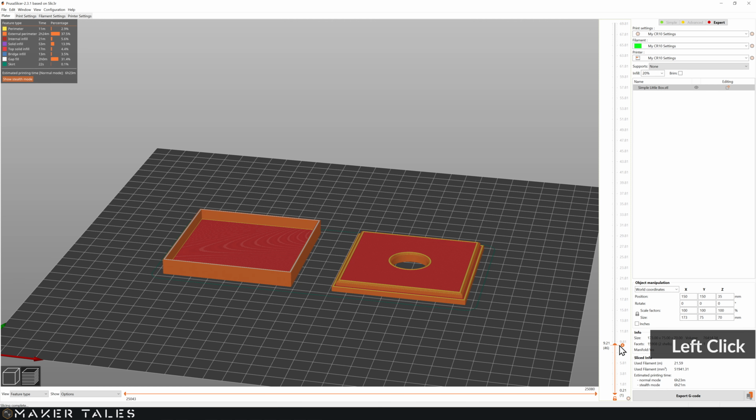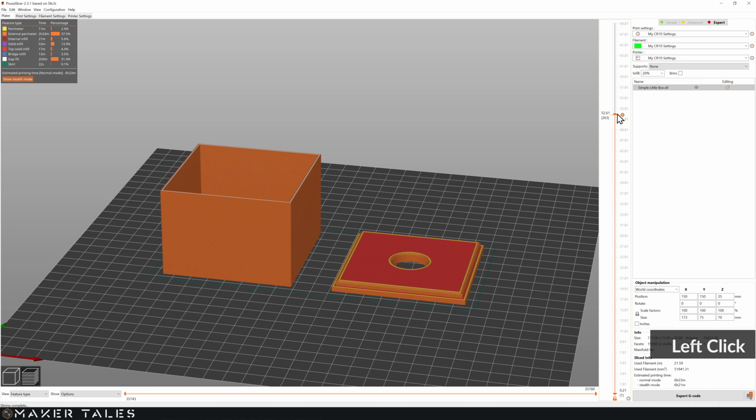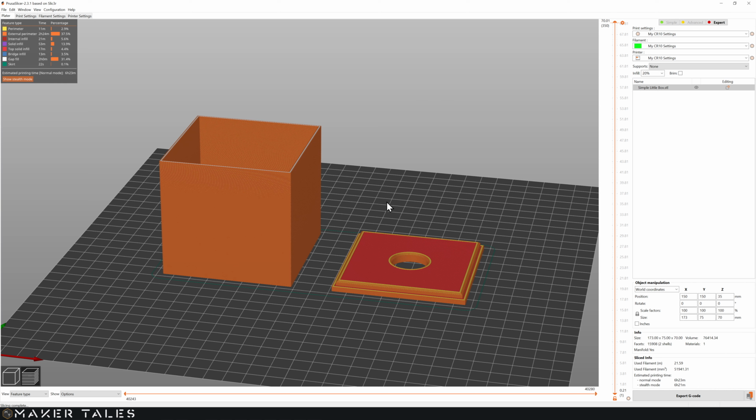That's perfect. There you have your first 3D printable project coming from FreeCAD, and you truly understand how all of it was created, what direct modeling is, and what direct reference modeling is. Well done for getting through that direct modeling video. I really do hope that you're starting to feel a little bit more comfortable with FreeCAD and seeing all the puzzle pieces sort of start to join together. As you can see, there are two very different workflows, both very direct in nature, one doing direct references and one applying just direct inputs from you. Personally, I use direct reference modeling about 80% of the time.